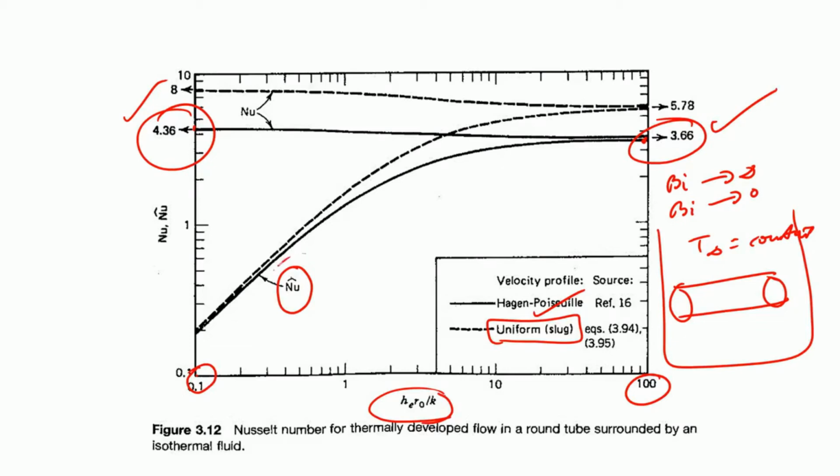This is of course the external Nusselt number, which was based on a nu that we wrote in our previous lectures. So, that varies in this particular way, as you can see from this graph. This basically completes the pending discussions that we had. We have now given, graphically as well as in the form of a table, how these constants will vary and what the nature of these profiles will be. Remember, all these equations were solved numerically.